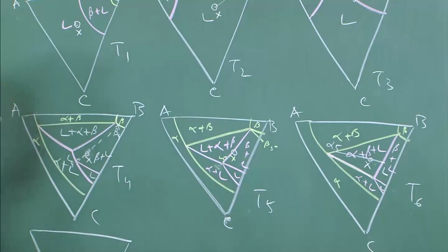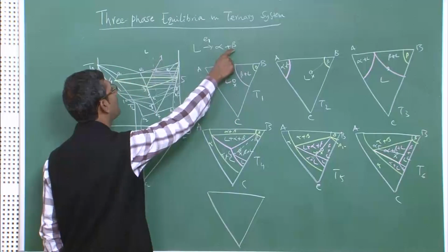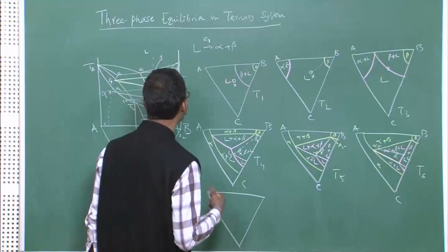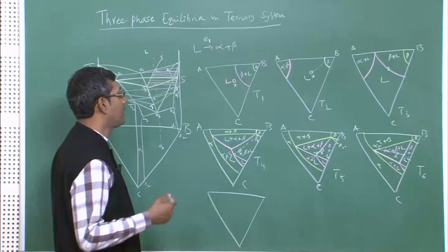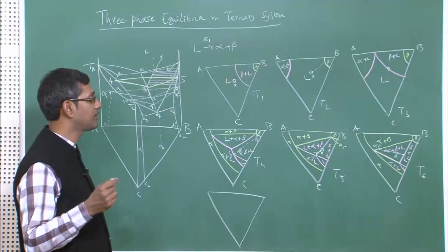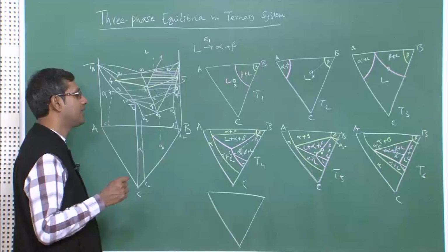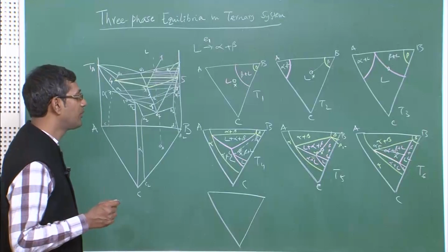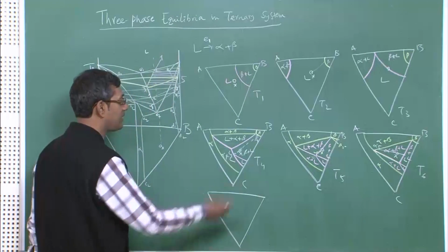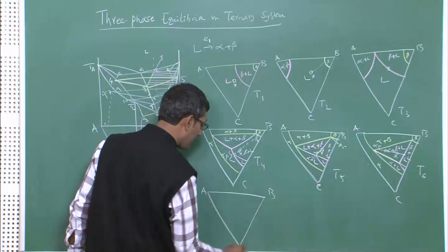So, what does it mean? It means that at this temperature a eutectic reaction is happening, leading to formation of alpha, and beta obviously will precipitate, beta was precipitating earlier also. So, as compared to binary phase diagrams, where the eutectic reaction or the 3 phase equilibrium takes place at a fixed temperature, so it is basically a non-variant reaction, here you have a monovariant equilibrium. Because of that this eutectic reaction can take place over a larger temperature zone, and that is what you see here. Although it has started forming here, it will also keep forming at lower temperature.